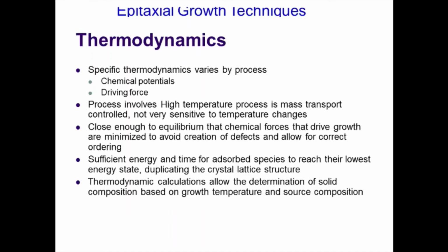Say, for example, if gallium arsenide is getting deposited on a gallium phosphide substrate, the gallium species try to join with arsenic species from arsine, and gallium again from trimethyl gallium. Okay, so the gallium species get attached with arsenic and form gallium arsenide on the substrate. It can be gallium arsenide or indium phosphide or indium arsenide, whatever the case, but it all depends upon the device structure you try to prepare.